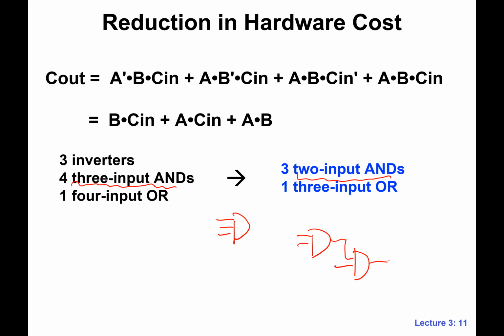Yeah, I have a quick question. Just to clarify, you first start by writing out a truth table, then you figure out the product of sums or sum of product. And then once you've calculated that, you simplify and come up with a simplification of the equation that will give you your original truth table. That's the workflow, right? That's right. What's your question, Jacob? I was just clarifying that. Basically we do the canonical sums and products just to put ourselves in a position to simplify later on. Exactly. Gotcha.